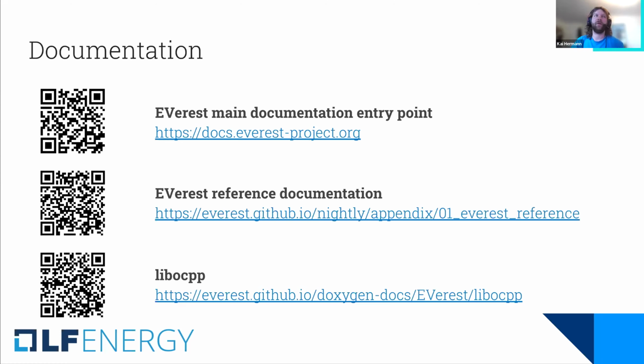If you want to have a look at the outward-facing MQTT API, this is done via the API module, and this uses a really simple MQTT API that you can, for example, bridge towards something like home energy management systems or home automation systems like Home Assistant, and interact with EVerest over that.